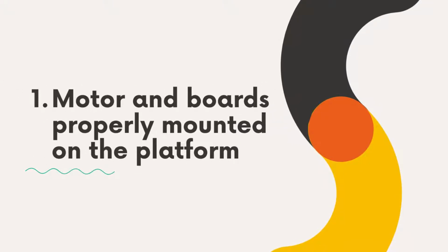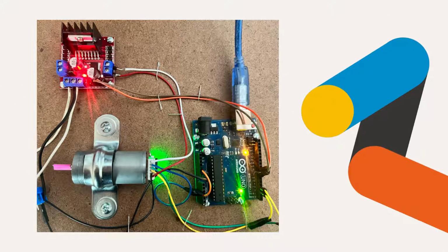Talking about the components that we use during this experiment. The first one is the motor. This is a GM25370 model that has an encoder and also a gearbox. This is really important because this motor has 140 revolutions per minute, and the gearbox works with a ratio of 1 to 45, and we have 495 pulses per revolution. We think this is a great component for this experiment.